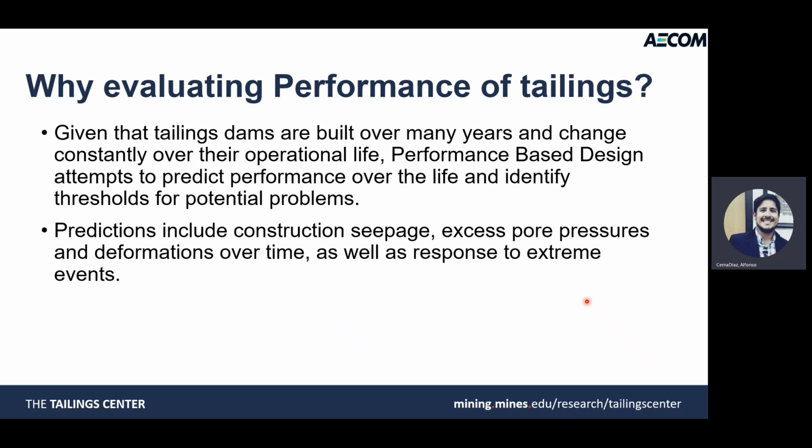There could be, for example, a dam crossing during impoundment. There could be some restrictions in spacing. Therefore, instead of increasing your dam laterally, you have to increase it up, and that typically induces more shear stress in your dam. You have seepage conditions, you have some foundations that are not very well drained, so you have very, very different aspects, not only in your site, but also during the life of your dam.